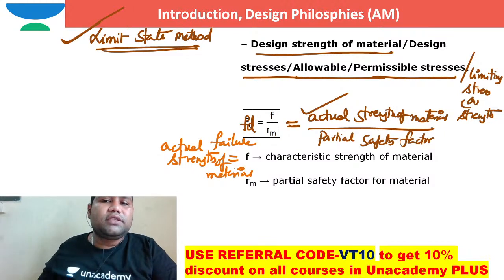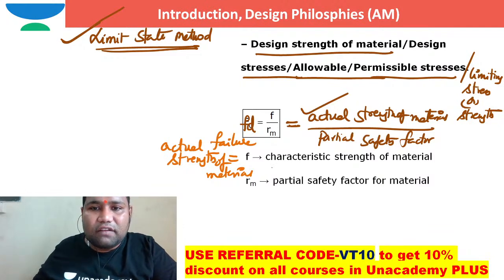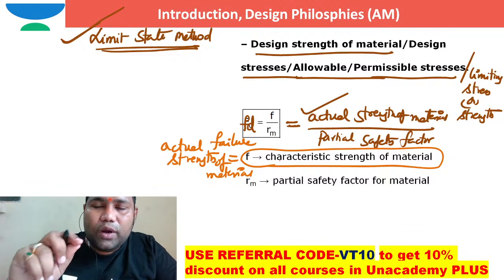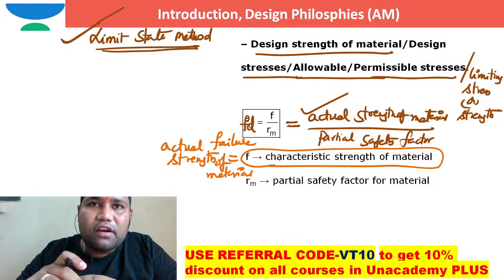Now the question is, sir, how can we define the characteristic strength of the material or actual strength of the material? Is there any definition, laboratory wise, like the load at which the material is failing, the stress at which the material is failing? Generally for concrete, it is the characteristic compressive strength of concrete, fck. For steel, it is the yield strength of the material.